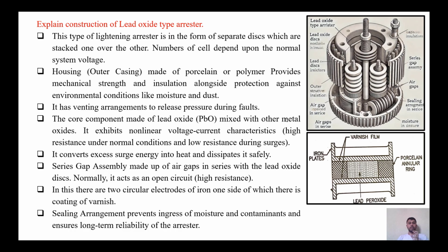The core component is made up of lead oxide, mixed with other metal oxides. It exhibits non-linear voltage-current characteristics, that is high resistance under normal conditions and low resistance during surges. It converts excess surge energy into heat and dissipates it safely into the environment.